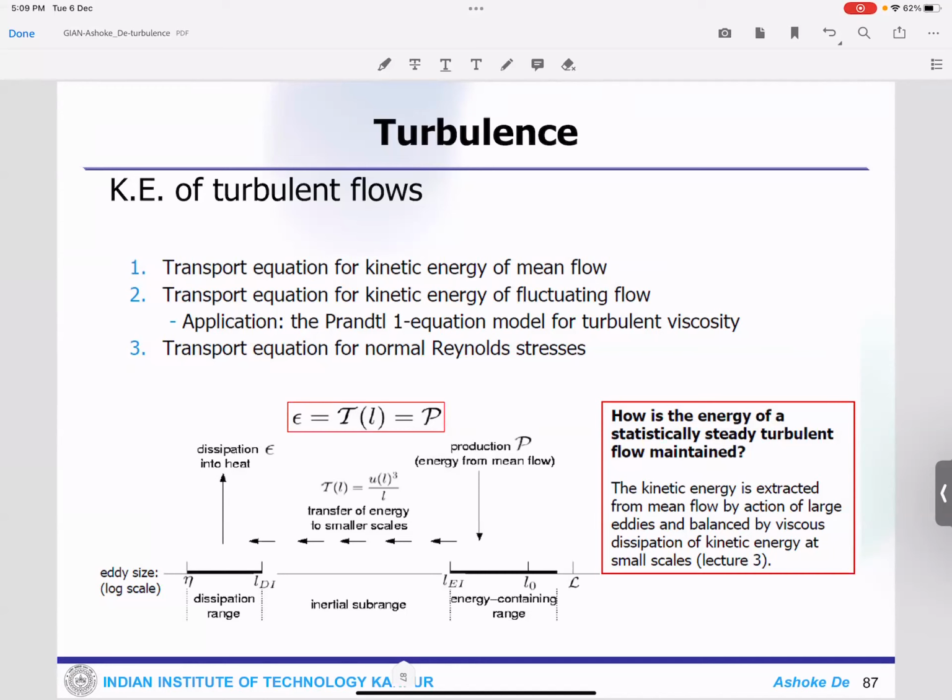Yes, but if we go to very high Reynolds number? Even if you go to high Reynolds number, the characteristic length would be of the order of that D only. It cannot produce any elliptical shape eddies. Okay, so it is not possible? No, it is not possible, because this is a very much geometry dependent property. Whatever your geometry, the large scale structure of the eddy would be of that size, that length. That would be the characteristic length. But when it transports and smaller eddies are formed, at that time it can take that shape due to vortex stretching and the vortex rotations, and that is possible. But at the beginning, it cannot take that shape.